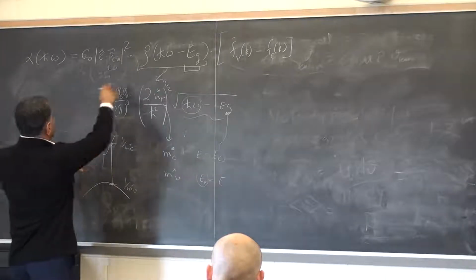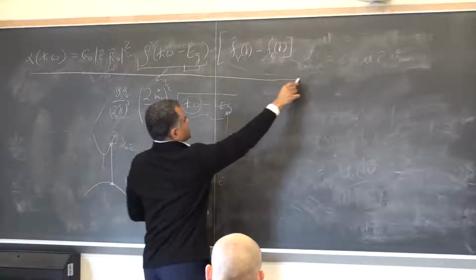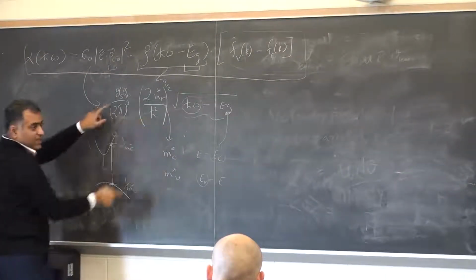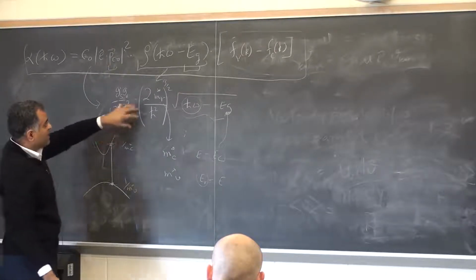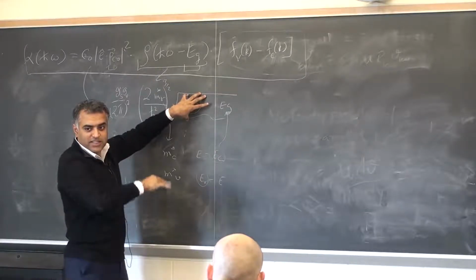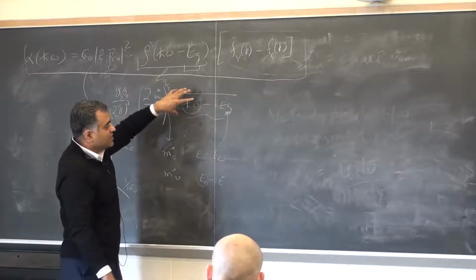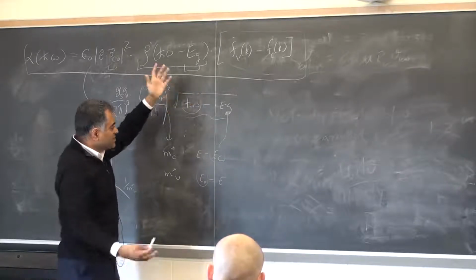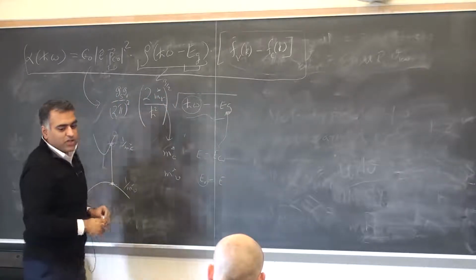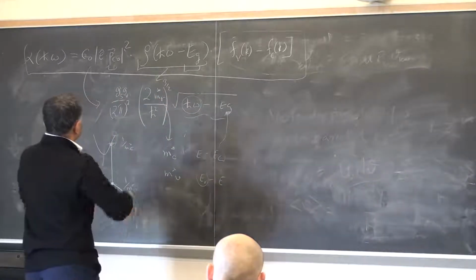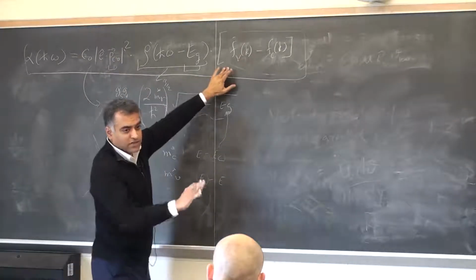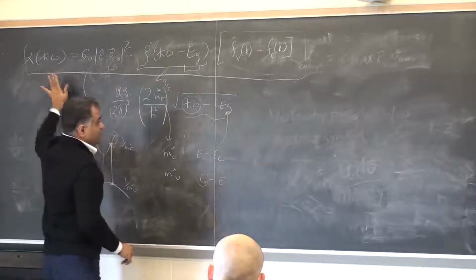Now this is a very general relation. Specifically, if I have a 3-dimensional bulk semiconductor, this is the result I will get. But if I have a quantum well, then instead of the 3D looking picture, you will get a step, just like the density of states of a quantum well looks like steps. For quantum dots or quantum wires, it will look like more discrete functions. Basically the density of states shape will change, but what will not change typically are the terms sitting in the front, and the Fermi function difference is not going to change. And that's your absorption coefficient.